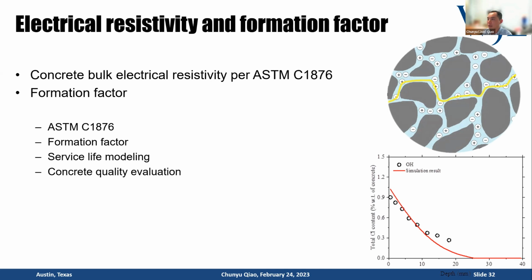So here I just want to focus on electrical resistivity. Concrete conducts electricity, as we know. So why? Rocks and sand do not conduct electricity. So it's only the pore solutions, more exactly. The pore solution in the matrix pores is the medium that conducts electricity by the mobility of the ions inside. So we have alkali ions, we also have hydroxide ions and other minor components of ions in the pore solutions. Those are the medium which make concrete conduct electricity.